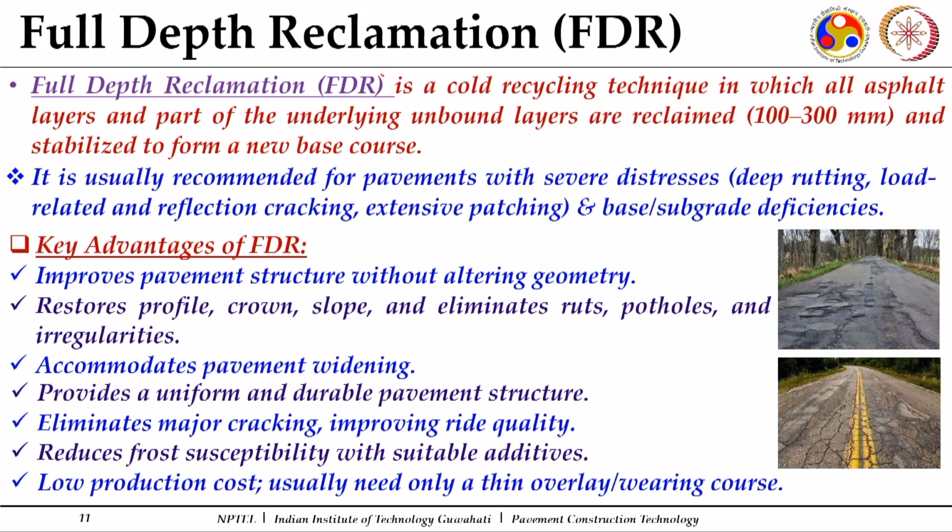Now comes the other part, which is full depth reclamation. As I mentioned, this is where you go for greater depths, in the range of 100 to 300 mm. So, if certain distresses are taking place because of underlying courses, that may be your unbound base courses showing some distresses, or your unbound granular sub-base courses showing some distresses, in that case we can go for a greater depth, and this can be recycled to produce a stabilized base course.